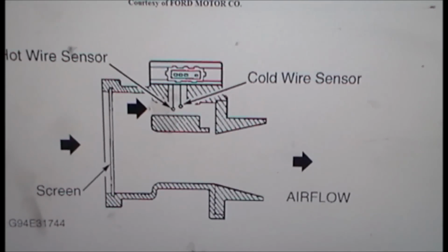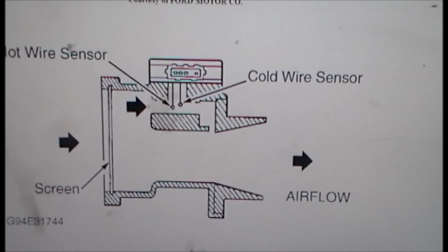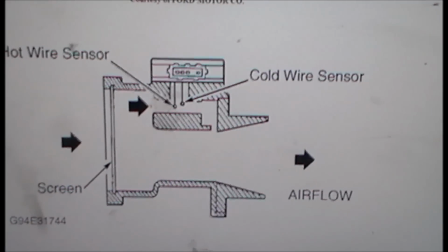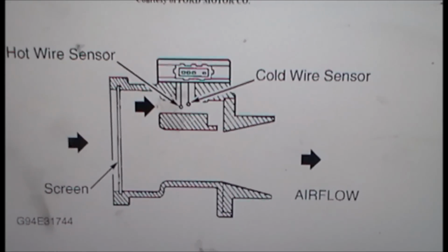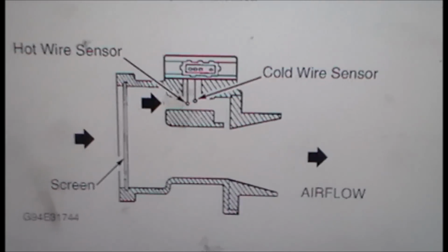You should see your fuel trims go negative on the short term, while the long term is still positive, and then you'll know it's fixed. So I'll take it apart, see if we can get a good picture, clean it off, and give it a shot.